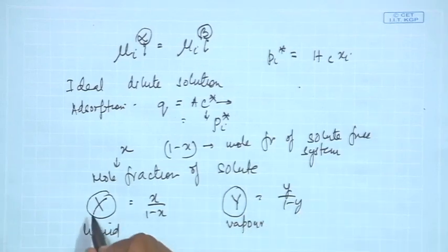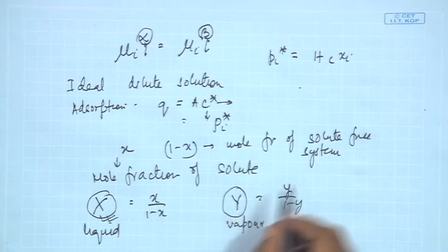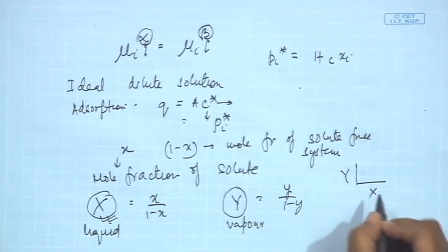The reason for often preferring mole ratios to mole fractions is that these often lead to linear plots. Capital Y versus capital X often leads to linear plots as compared to small y versus small x. Once more, when we are dealing with gaseous components, very frequently the concentration unit which we prefer is the partial pressure. So, partial pressure in the vapor phase or gas phase is often preferred for absorption, stripping and adsorption as well as leaching.